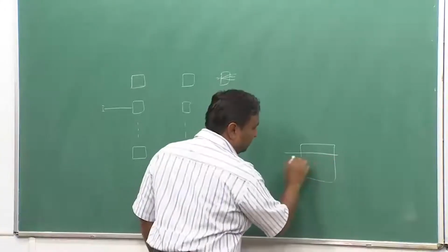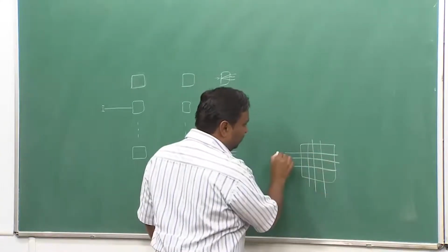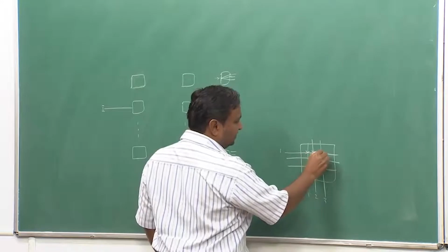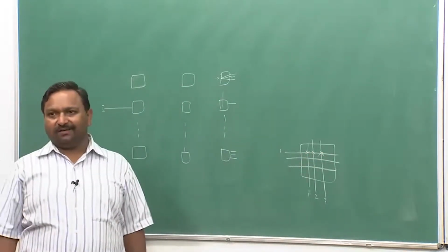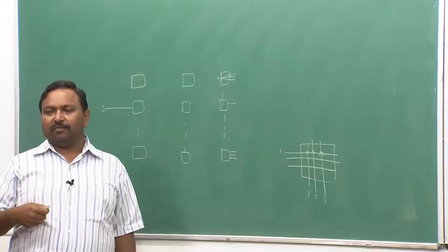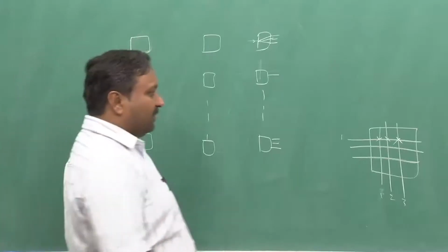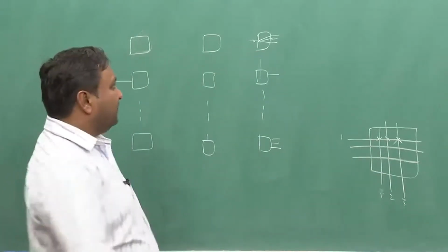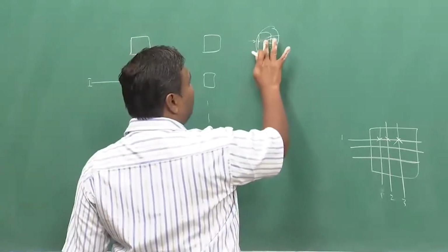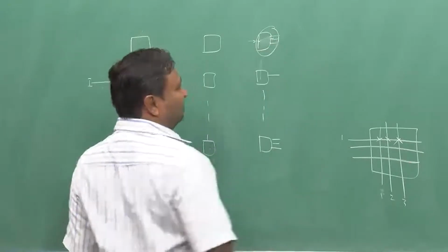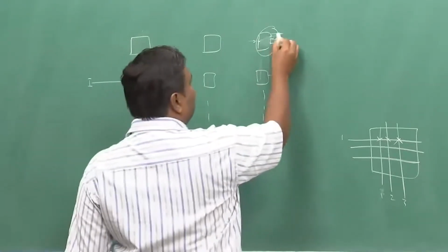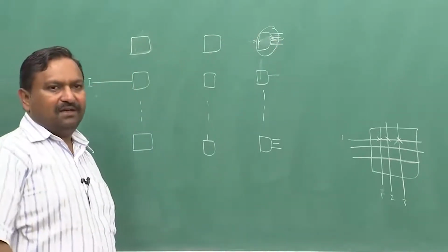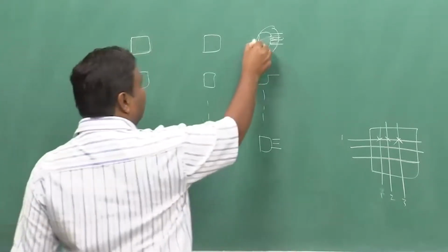So, in a crossbar, when I want to do a multicast from 1 to say all the ports, I just snap all the cross points together. So, the duplication or multiplication in a multicast system happens within the crossbar. One input can be feeding two outputs, and so this is a strictly non-blocking system. So, I should not worry about the multicasting if there are multiple inputs here. Even if there are multiple outputs which have to be connected to the same input, I should only bother about how I will be able to send the signal here.